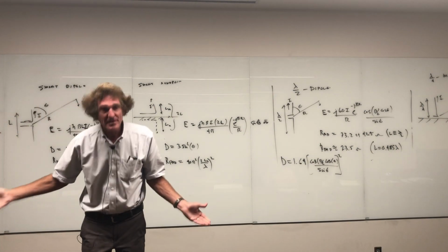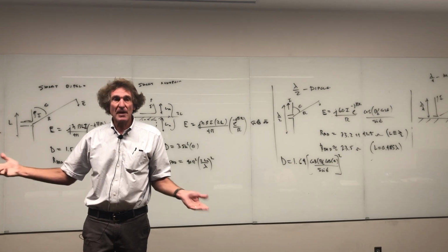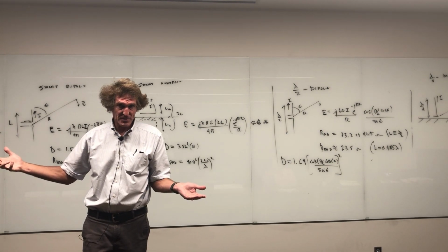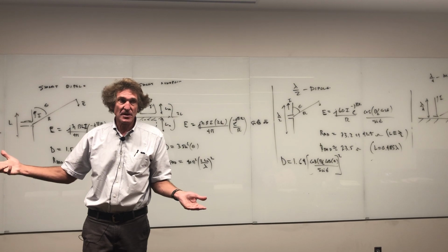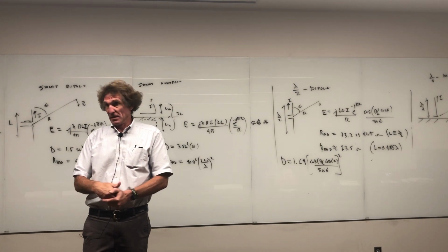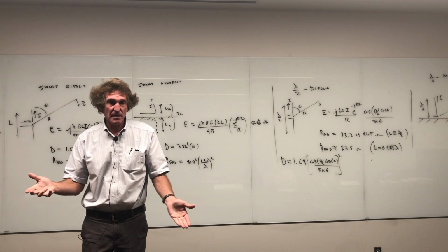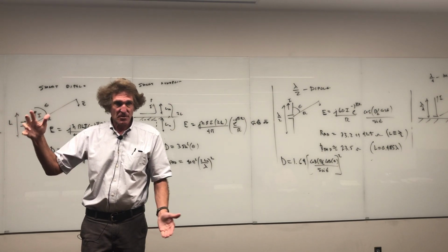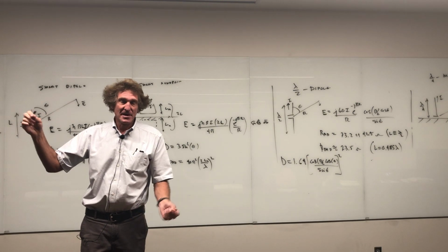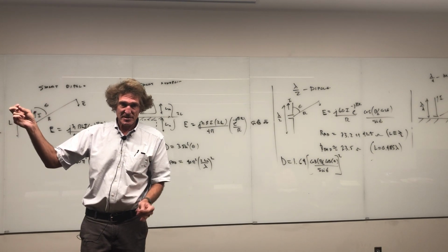The thing about water is it takes an enormous amount of energy to heat it 1 degree. And so water is the ideal thing if you need a resistor that can dissipate lots of energy fairly quickly without boiling or heating up and burning up. That's how they do it. It's called a water resistor. You can look it up. I learned a lot doing that railgun project, and this is one thing.